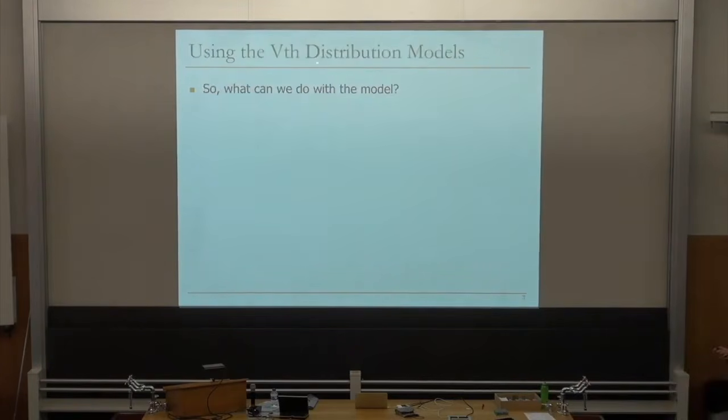Basically, remember, we developed models for threshold voltage distribution. Threshold voltage determines the value that's stored in a flash cell. And you have a threshold voltage range, and you chop it up into smaller sub-ranges. Each sub-range encodes a data value, right? It could be in an MLC, multi-level cell NAND flash, 00, 01, 10, 11, 2-bit flash. But there are flash memories that are 3-level cells right now. It's called 3-level cells, unfortunately, but it's really 3 bits encoded in a voltage range. It's really 8 states. In a sense, it's 8 levels, right? It's not 3 levels, but it's 3 bits. And people are looking into encoding 4 bits within the voltage range, right?